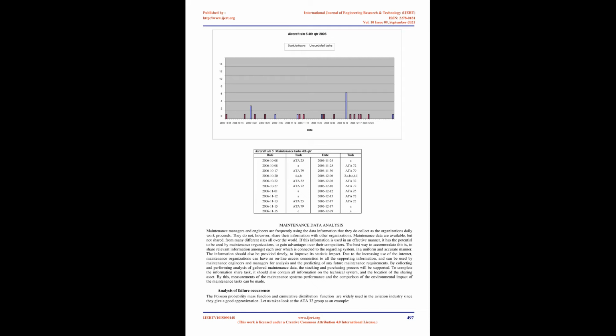Notice, this is only valid for short distance flights. Determine the scheduled maintenance. All scheduled maintenance tasks in the AMP were studied, inspections and replacements, based on cycles and monthly intervals, were translated into runtime hours based on the assumptions made earlier in Chapter 4.2 above.